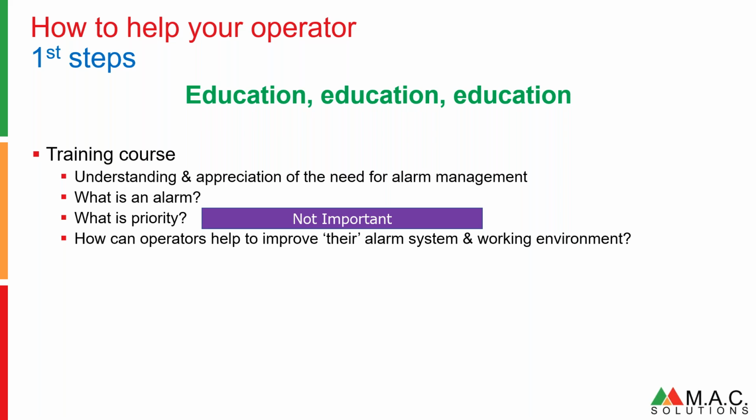They turned the alarm sound down, so they just had to look for things happening rather than being alerted by the noise, the sound alerting them to the fact there was an alarm. They just had to keep looking. So if they have lots of alarms, it's going to be a noisy system. So I deal with, when I do the alarm management training courses for operators, how can you help yourselves?